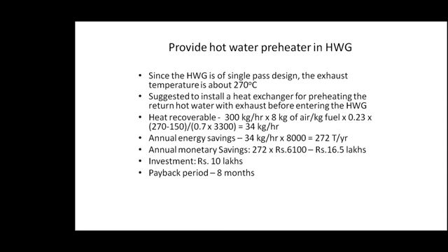And the hot water generator. Instead of a steam boiler, here they are using a hot water generator. It's called a pressurized hot water generator. You increase the pressure of the steam. As you increase the pressure, your boiling point increases, so you can circulate the water at a higher pressure and higher temperature. So that is the pressurized hot water system.